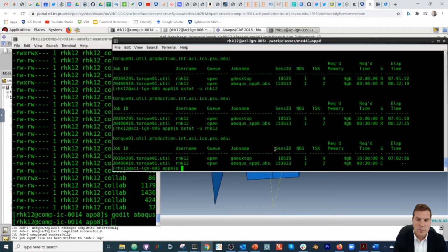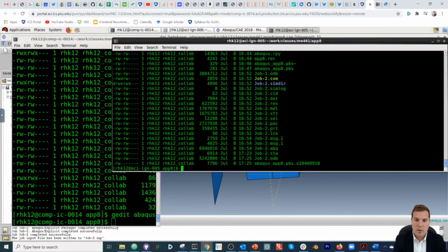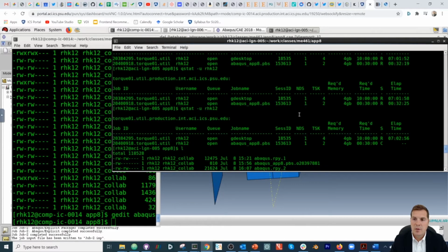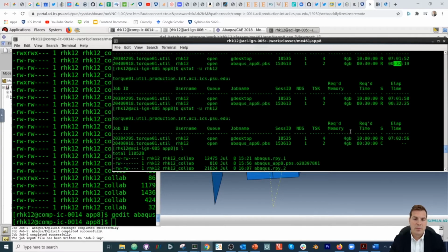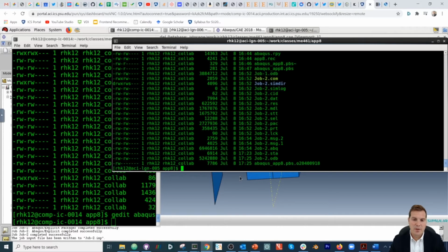Okay, that job completed. Now, I don't think it actually finished because it was running up all the way until like 30 minutes, elapsed time's 32, and it didn't finish yet. So, you know, I haven't looked at it yet, but it might be a sign that I need to extend my PBS wall time, say, to an hour and let it finish. But let's open up and take a look at it.